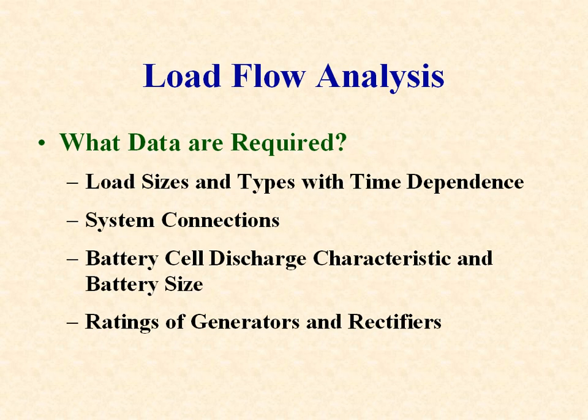A load flow study requires generally the same data as required for battery sizing. The critical inputs are the load sizes, types, and time dependence, along with the system cabling and connections. The load flow also needs the battery characteristics and size if the system is supplied by a battery. If the system is supplied by generators and/or rectifiers, the ratings of these components are also required.